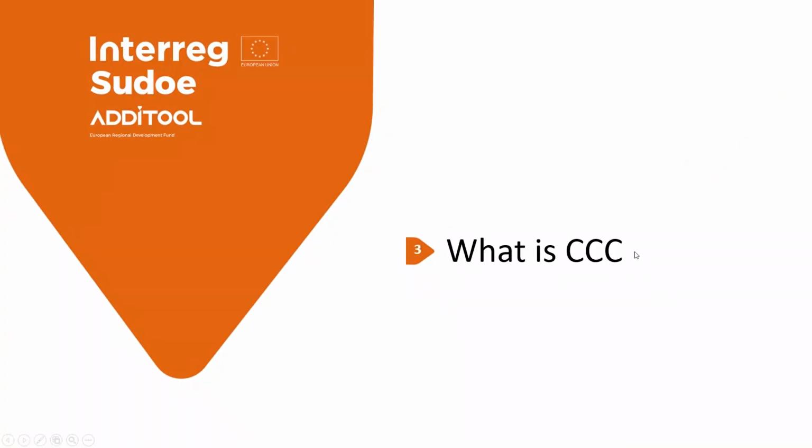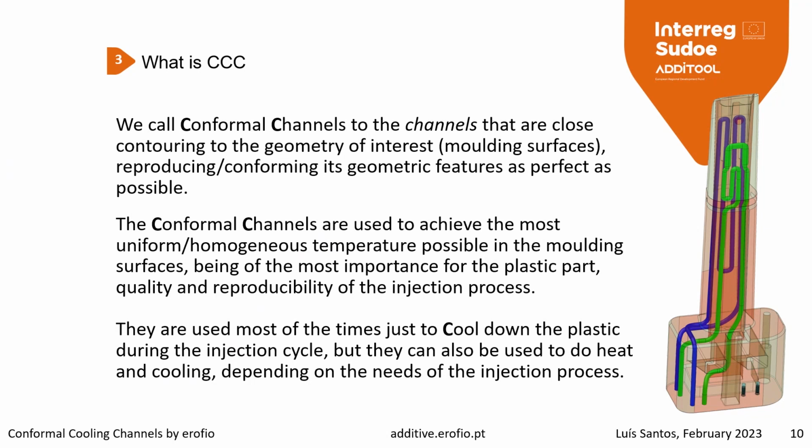Now, our main subject: what are conformal cooling channels? A small definition: what we call conformal channels are channels that closely contour the geometry of interest. In our situation, it's the molding surface, reproducing and conforming to its geometric features as perfectly as possible. Conformal channels are used to achieve the most uniform, homogeneous temperature possible in the molding surface. That's one of the goals, the best goal that we want.